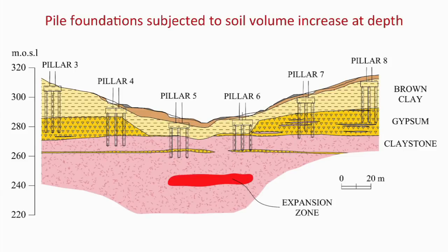Now, this is a bridge in the high-speed line between Madrid and Barcelona. It's a 600 kilometers long line, but this is in Catalonia already. And these pillars are 50 meters high. And then, for reasons that I cannot explain here in detail, this area here, this volume here, began to expand. Now, those pillars are 50 meters high, but the piles are 20 meters long. They are covered by a cap, which is very rigid, something like 4 meters or so of thickness of the slab. And the piles are 1.5 meters in diameter, so it's a big foundation. 3 by 3, so 9 piles for each one of these pillars.